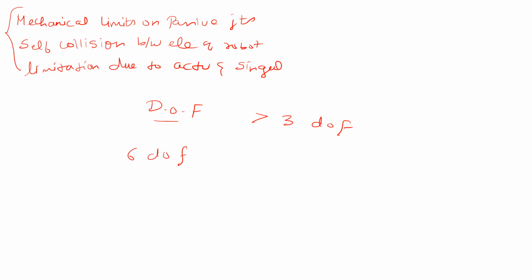The 3D volume depends only on the motion capability of the first 3 actuated joints, while the orientation will be using the last three joints.